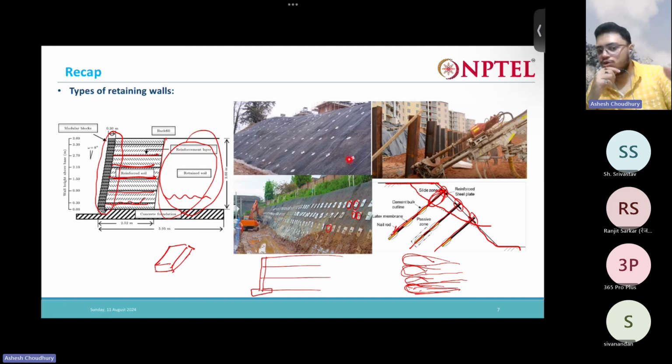Okay, and in the video also he clearly explained everything very properly, right? So you saw the experiment, this small demo. Initially without the nails, the slope was taking a lesser load, but when he put the wooden nails in the model, the same slope could take a large amount of load. So this is the main use of soil nails.